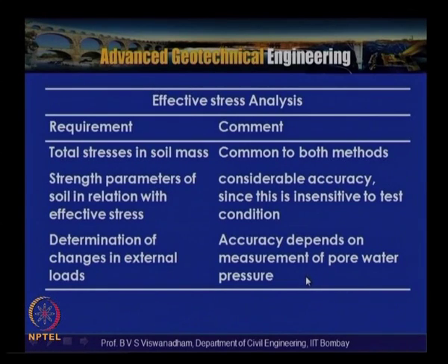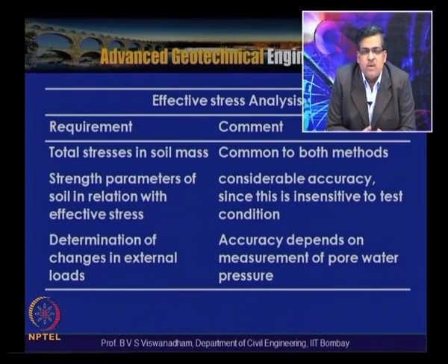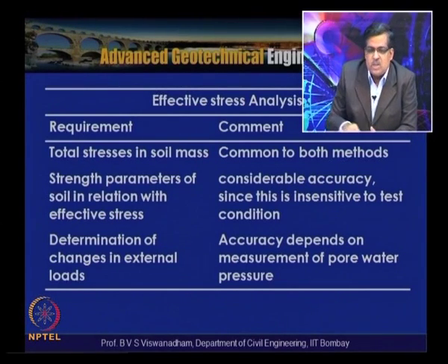In the effective stress analysis, here also we require total stresses in the soil mass, which is common to both methods, that is, effective stress and total stress analysis. The strength parameters are in relation to the effective stress, and there is considerable accuracy since there is an insensitivity to the test condition and the determination of changes in external loads. Accuracy depends upon the measurement of the pore water pressure in this case.